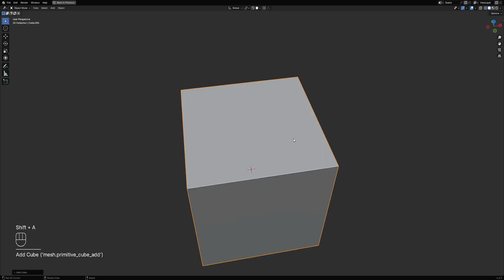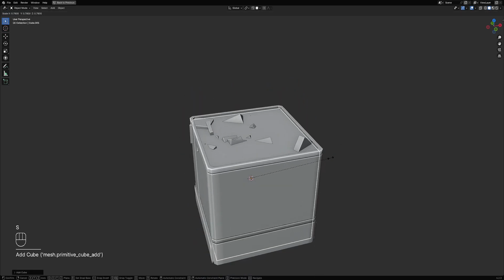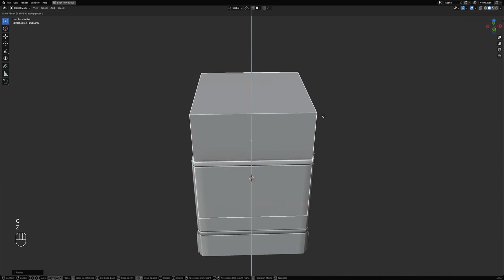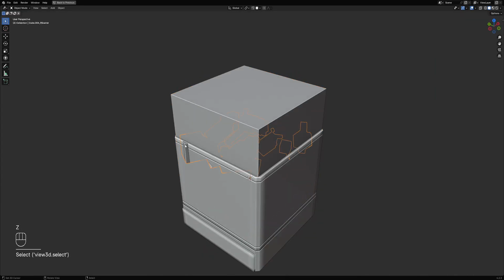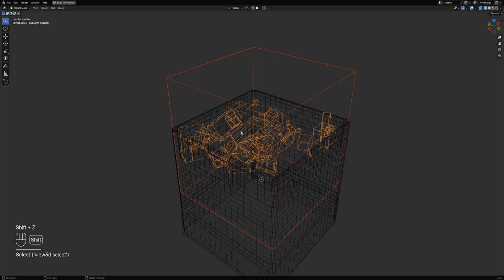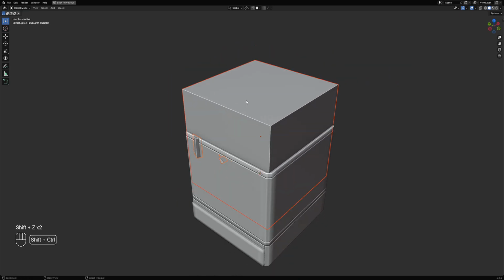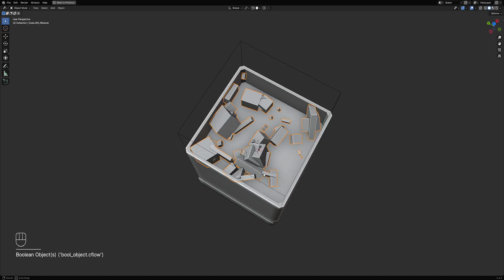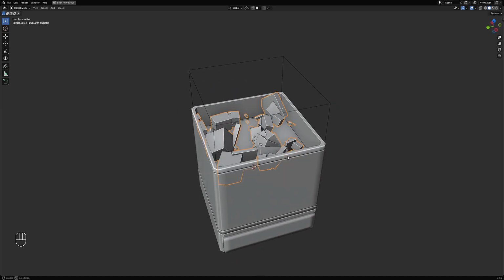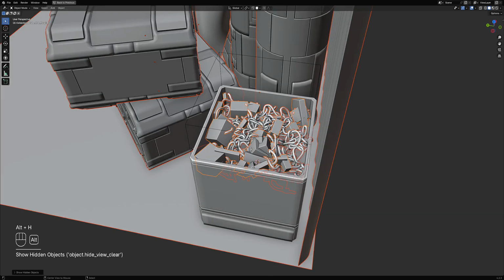And you can also do this. You can add the cube once you position the 3D cursor correctly, and then increase that. Select the cube and then the source object or the design object, then boolean objects, boolean to active, okay, boolean to the source object, which is our active object, and intersect. So that's how you can do it with creative flow.